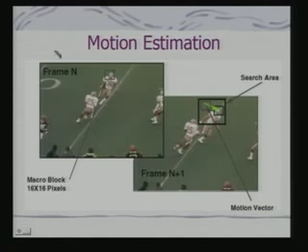So, when you use I and P frames, you can understand that DCT is obviously a time consuming block. And another time consuming block is your motion estimation, because I have to actually search in this image to find a match for this block to exploit this redundancy. In fact, what I have shown here is a search area, the bigger block is a search area, and I am mapping this block in the search area and I am moving this block around over the search area to find the best match. So, this computation is what I would like to accelerate.